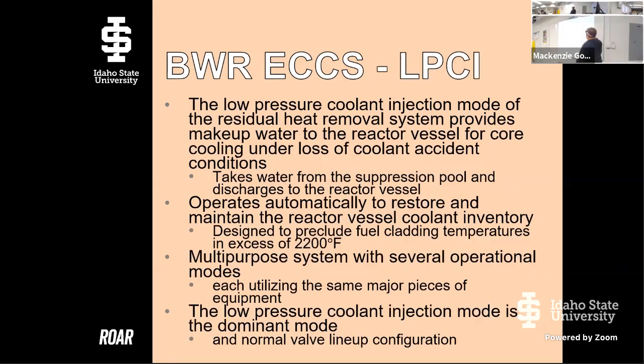And then that low pressure coolant injection system and our residual heat removal provides makeup water for cooling under loss of coolant accident conditions. There is a suppression pool underneath the BWR. It's going to essentially allow a lot of water access for all these ECCS, okay? It's going to operate automatically.